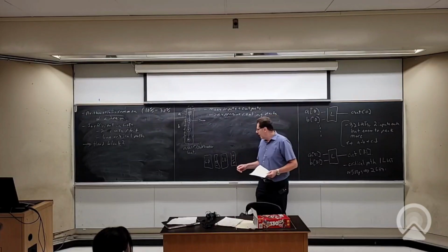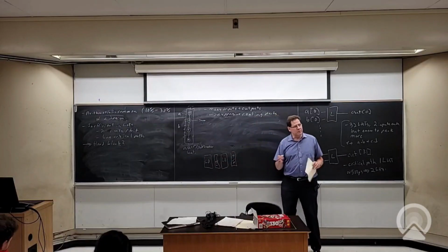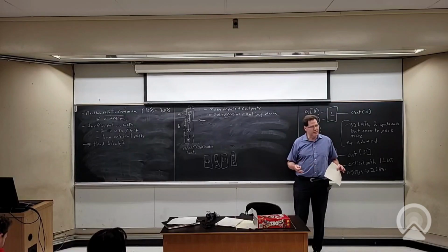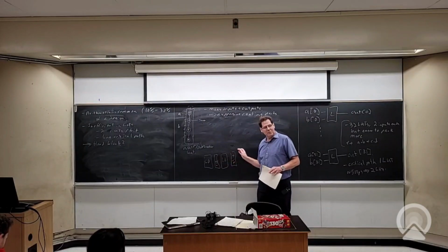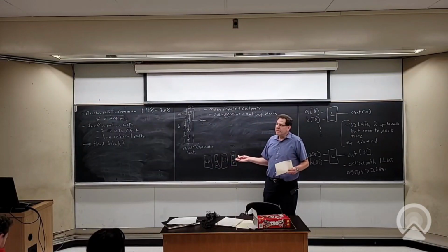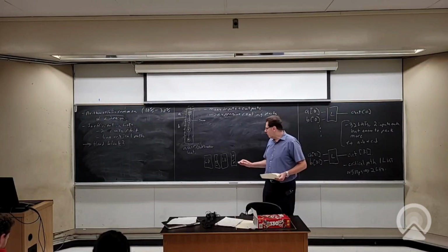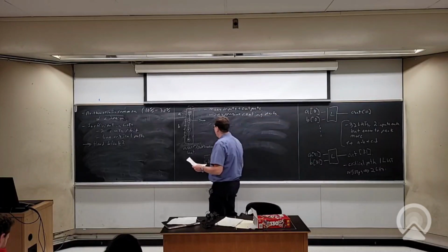So by having 2 different kinds of things, I will tend to stretch my wiring some. I am making the placement engine's job harder. And you could go, well, maybe the adders should be somewhat together, maybe the logic blocks could be somewhat together. There's no perfect answer. Every design will want it a bit different. Some designs will want more adders, some will want fewer, etc. So we're going to stretch some of the wires.